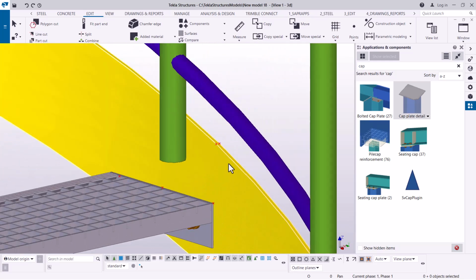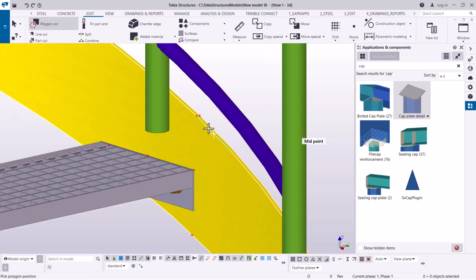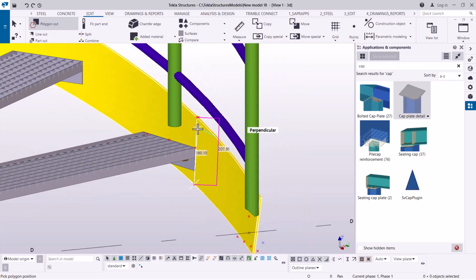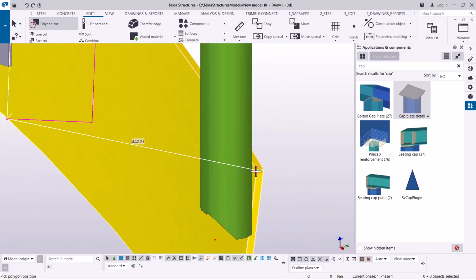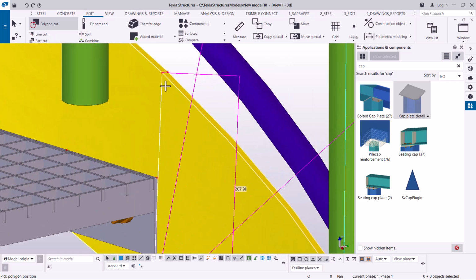It's somewhat tricky at this point, so let's do something once again. Let me pick polygon, and if I pick that, I'll snap on this spot, this spot, and this spot here. Let's try polygon to trim it off, and I'll be able to see whether we can trim it off.